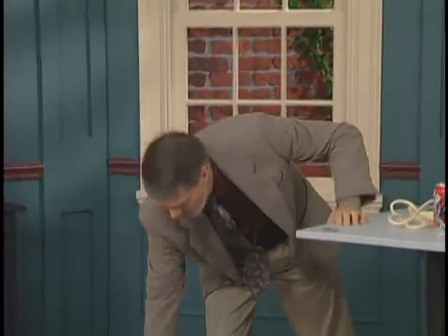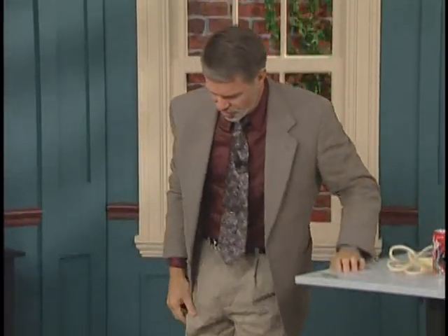Remember, a stack of paper is tremendously strong under compression, but it's easily pulled apart under tension. And by the same token, a nylon rope has exceptional tensile strength, but virtually no compressive or shear strength. And here's an interesting example. The relative strength of a soft drink can depends on whether it has liquid inside it. Now, look at this. Here's a Coke can that's full, and it can support my entire weight. I can stand on this can.